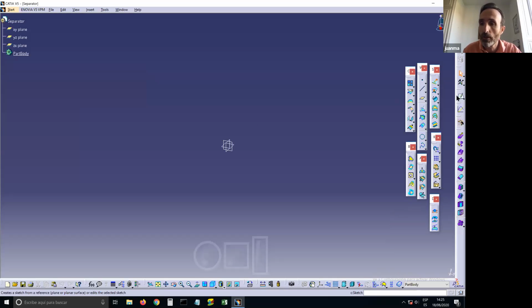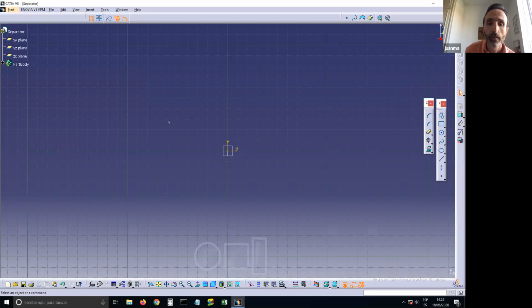First of all, I will do a sketch. You can imagine, if I want to draw a curve, I need a piece of paper where I can draw it. I need a 2D paper. So what I am going to do is specify which plane I'm going to use for drawing. I am already in a 2D environment. So I will draw the spine by means of several straight lines. I will set the length of this line, for instance, to 60 millimeters.